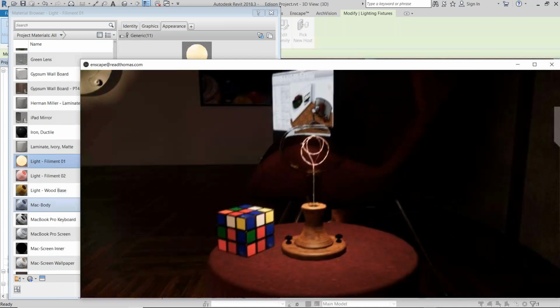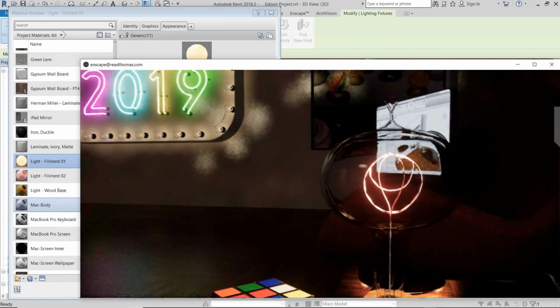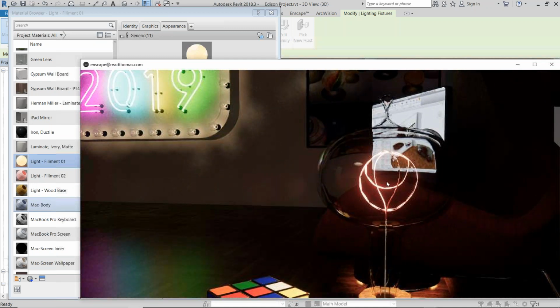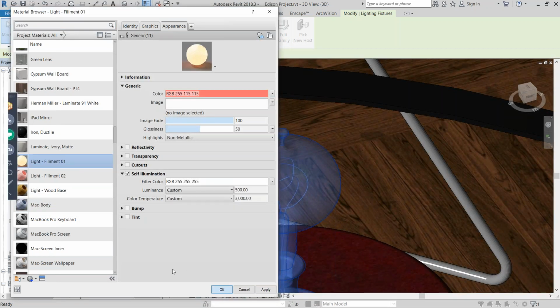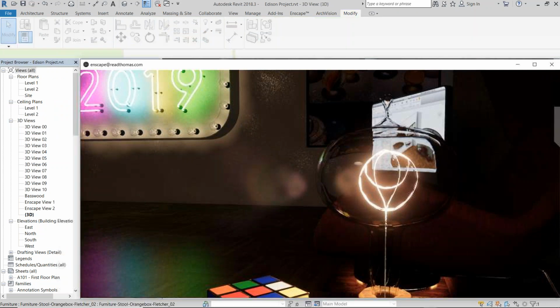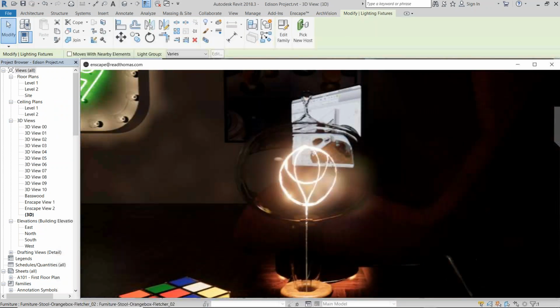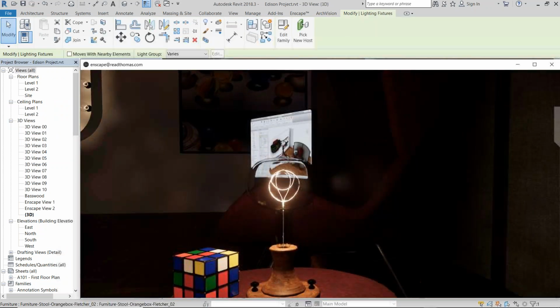And this is why it's noticeable. At the moment, you're seeing the appearance of light on that geometry, but it's really just the reflection of the light inside that family. Once we give that little piece of geometry luminance, here's the difference. Now that little bit of wire appears to illuminate, and it appears much more natural.